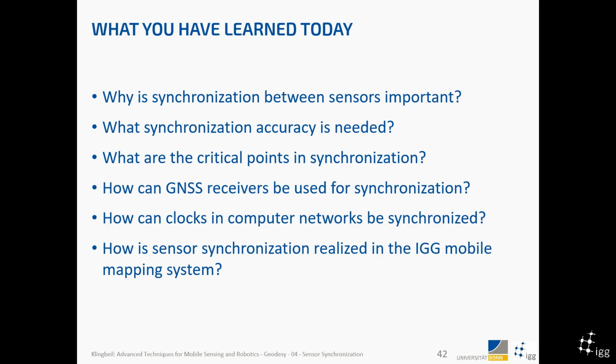If you drive a system through the city, where you work with like 20-30 centimeters accuracy, because maybe your laser scanner is anyway not so accurate, then it might be totally fine to go with 10 milliseconds accuracy. But if you go towards centimeter accuracy, then you have to really look for below milliseconds.